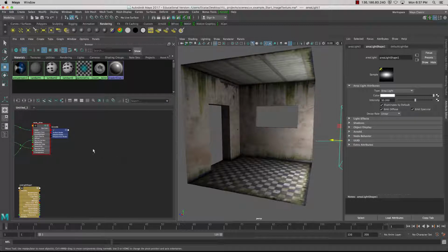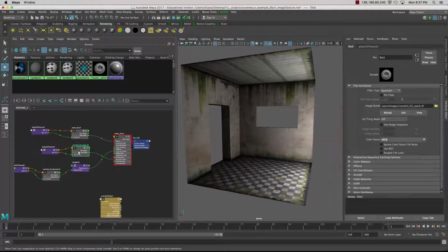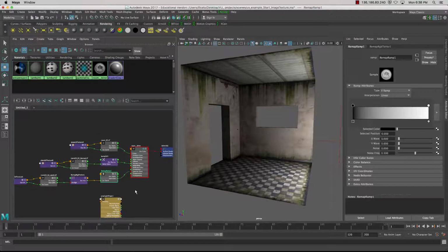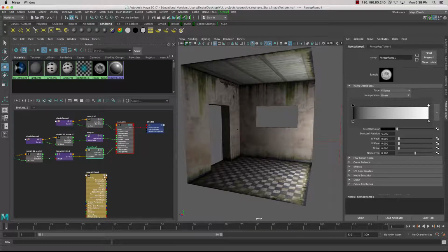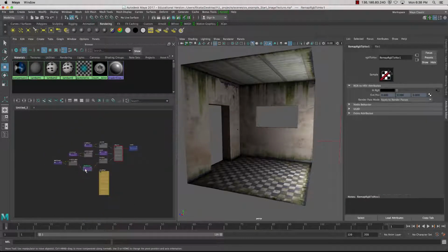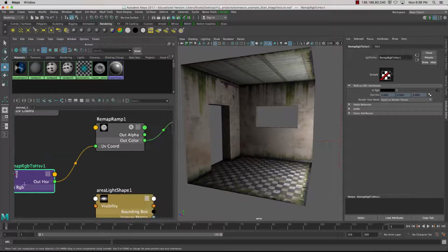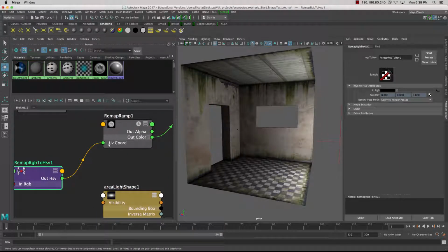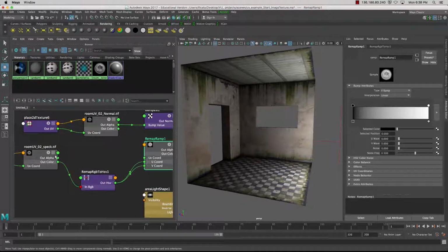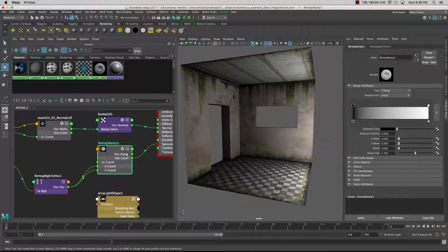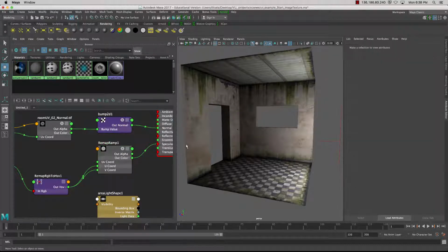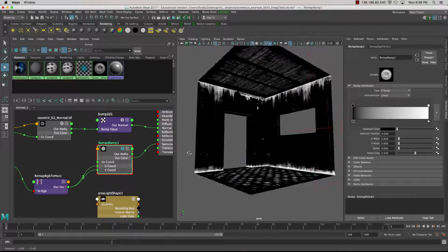and if we go into specular, and if I click on my specular, under effects, we've got this color remap. So if I click on that, I then plug in an RGB to HSV node from the out color, and then the out HSV goes into the U and V coordinates of this ramp. So what's cool about this is if I solo the texture, like so, there's my texture.